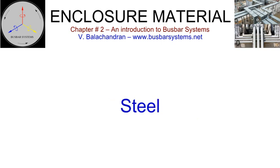Steel. Powder-coated sheet steel is used extensively as a bus enclosure material. Steel is economical, strong, and workable. The sheets are cold rolled up to a thickness of 4 mm, 5/32 inches. Since steel enclosures are more susceptible to corrosion, it has now become a normal practice to fabricate the enclosure with galvanized sheets to provide better environmental protection. Powder coating of galvanized sheets, to the desired color and finish, provides additional protection.